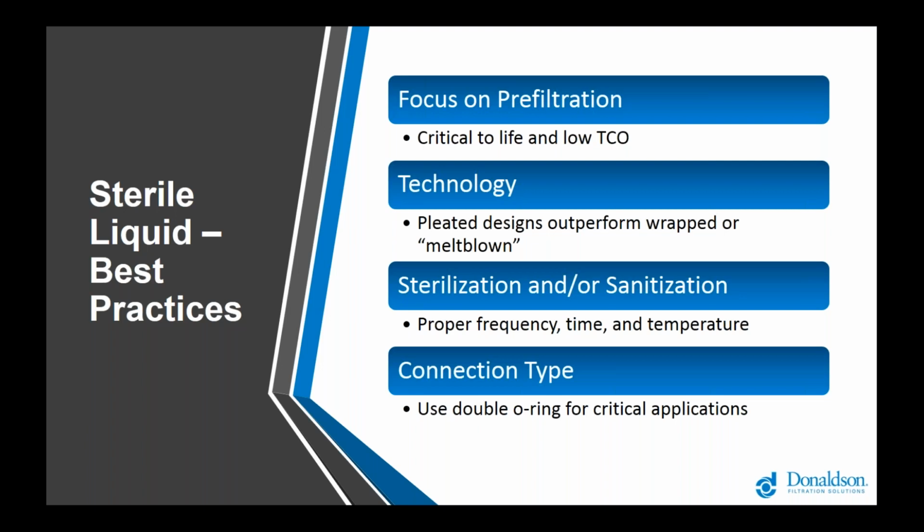that is really axially compressed between a couple of what are called knife edge seals, or just sharp edges in the housing that press into that cut off open end of the filter. And there's another design that's popular that uses two O-rings.